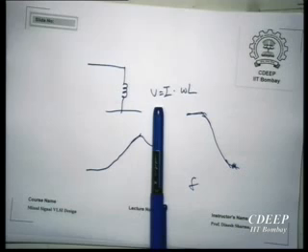So what is the famous thing about 8051 ports? The port driver. You have two drivers. Whenever there is a 0 to 1 change, there is one high current driver which dumps a huge amount of current for a short time. So when do you need current? When the voltage is changing. To retain the voltage, you require very little current, right? So as a result, what you need is essentially, if this is a pulse, during this time,